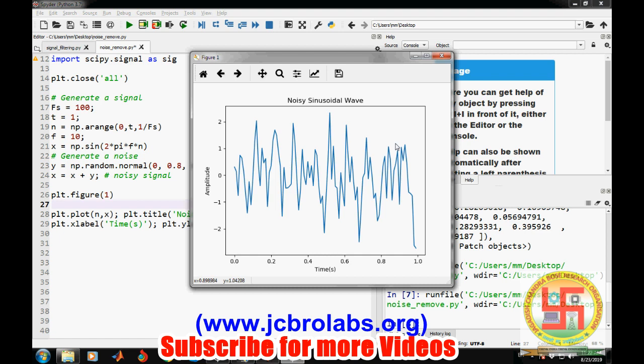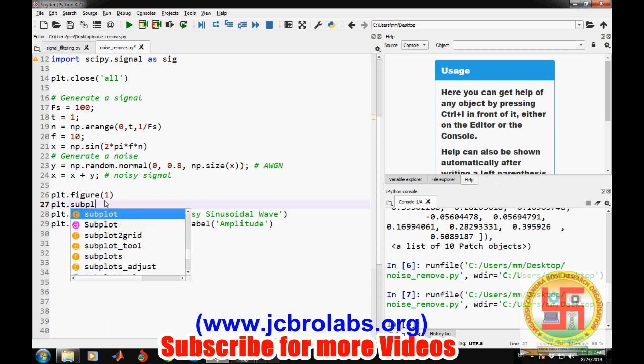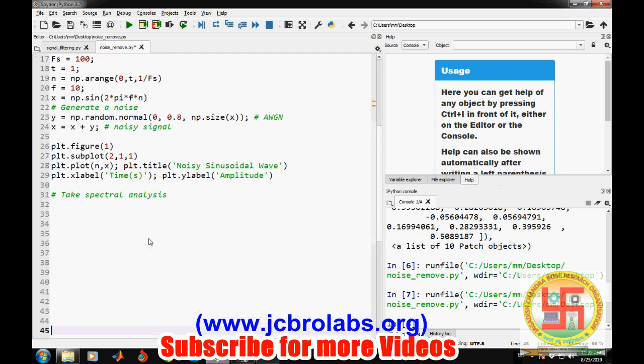Now from here the main task starts. First of all, we will do the spectral analysis of the signal. So plt.subplot(2, 1, 1). To do a spectral analysis, the simple task is to first take the Fourier transform of the signal. So let's have x_f equals the absolute value of sf.fft of x.